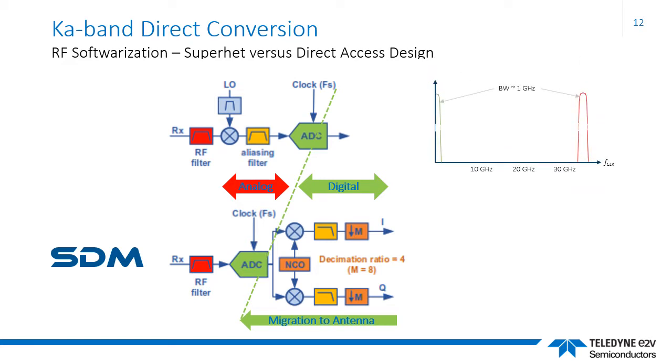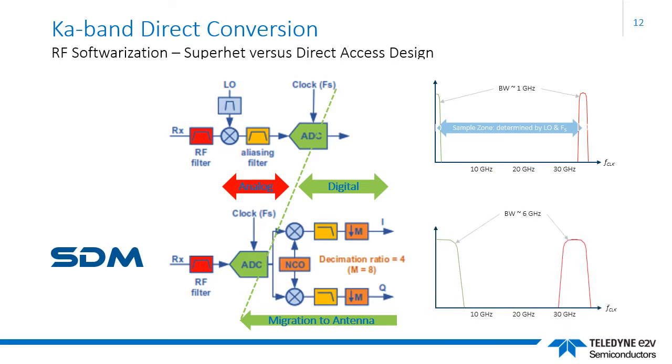Eliminating the need for IF stages and their local oscillators, radio design simplifies, and it is then possible to perform all the frequency domain processing in the digital domain alone. That means increased versatility for future air interface systems, as well as reconfigurability and enhanced frequency reuse.